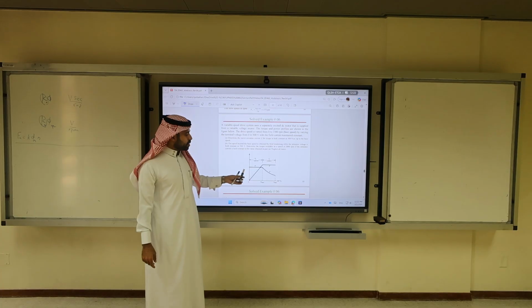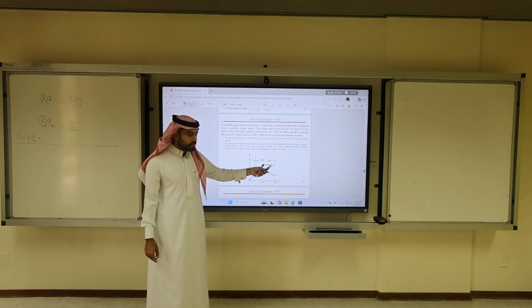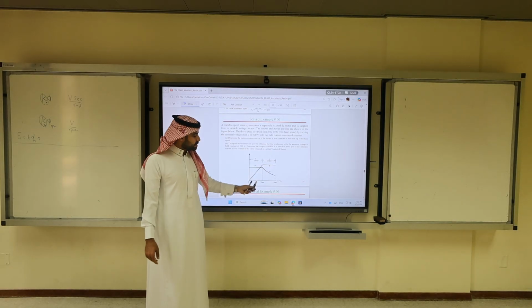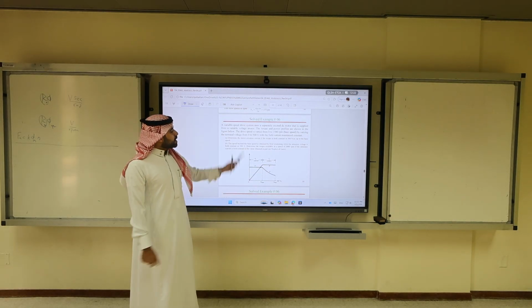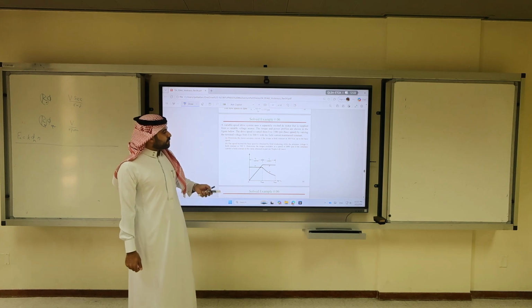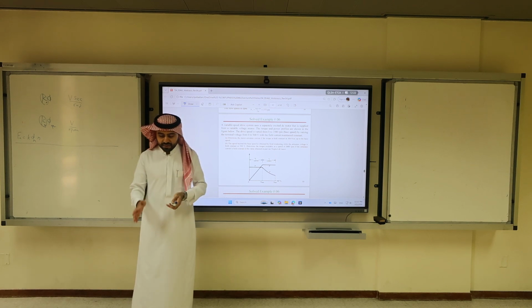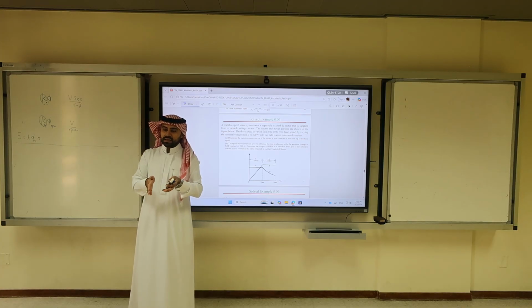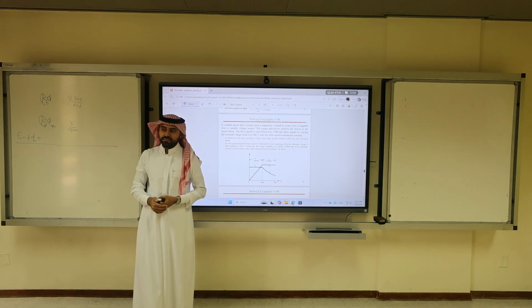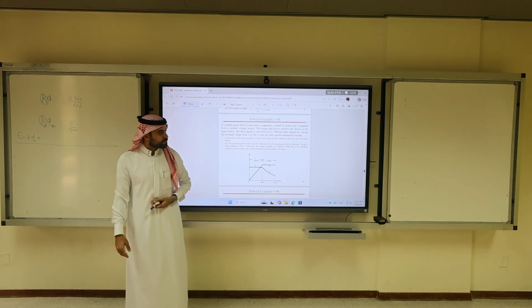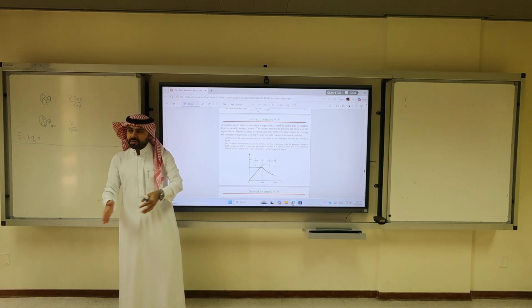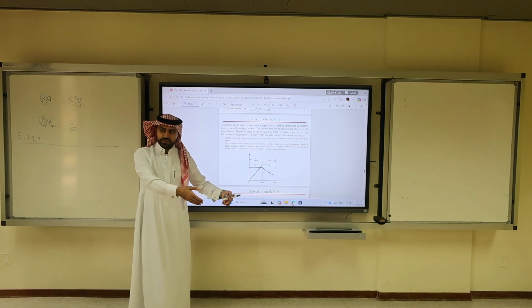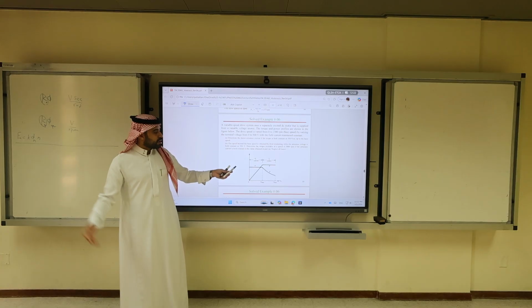So he's telling you we're doing constant torque, constant power operations until we reach omega speed, the drive speed. So basically a drive is power electronics plus your separately excited DC motors. It is capable of driving another machine, like two machines connected together. So that DC motor, maybe the variable speed drive would drive a generator, for example, like the machines experiment.